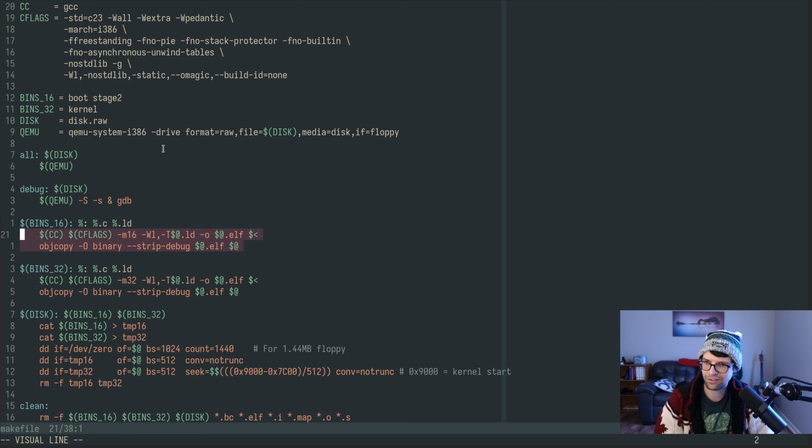But the reason I'm doing this in 2 steps is to have a flat binary that I'm running, but if I want to debug, I want the symbols for that, and I need somewhere to get those symbols from, such as the ELF file here. Or the object file, but the ELF has the actual addresses after linking, so that's more useful.